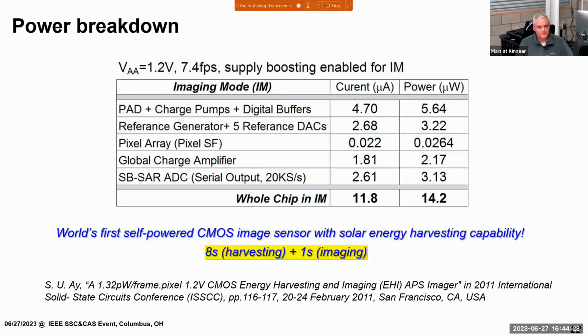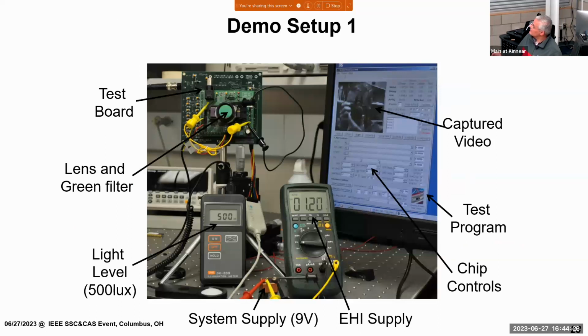But it depends on how you measure. If you look at this figure, this is the sensor for this lux meter. It looks up, and on top of it there's a light that directly sees it. If I flip it the other way, my way, it probably reads like 200 or 250 or so. It depends on how you place it. That's why this is there, so that you know where it is looking. And I can put this one upside down and say that this is 100, and then disclose it that way. But that's, again, not a good way to present.